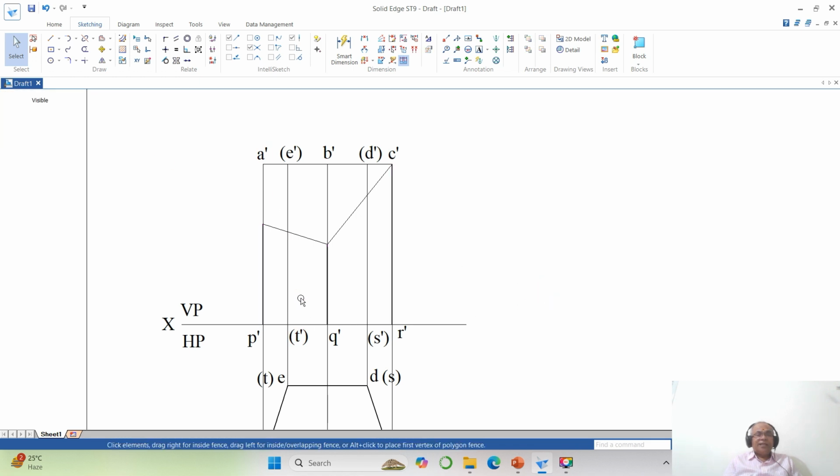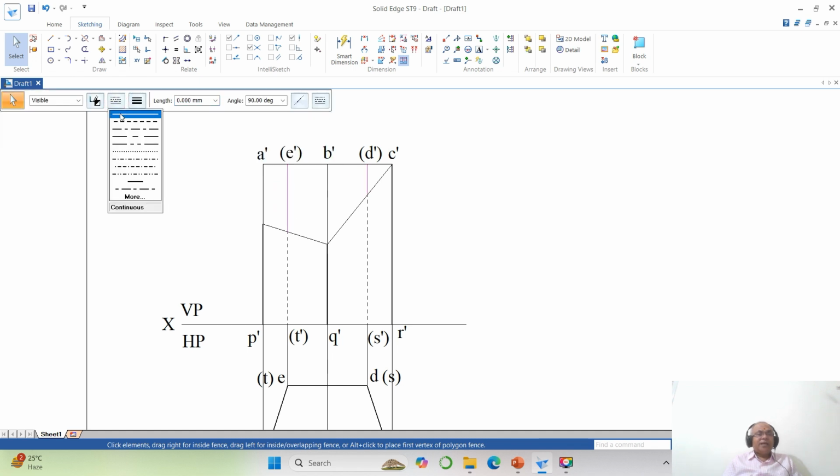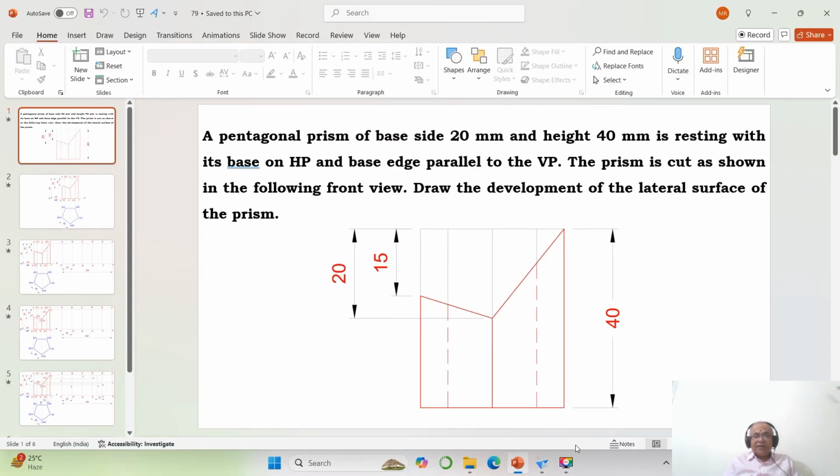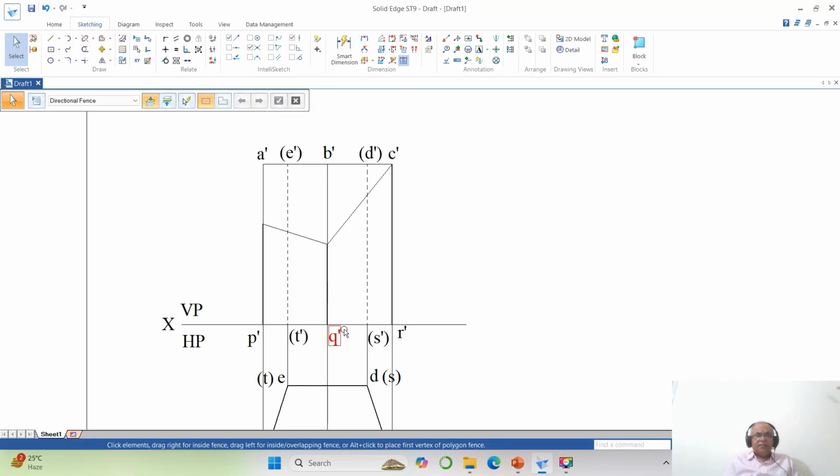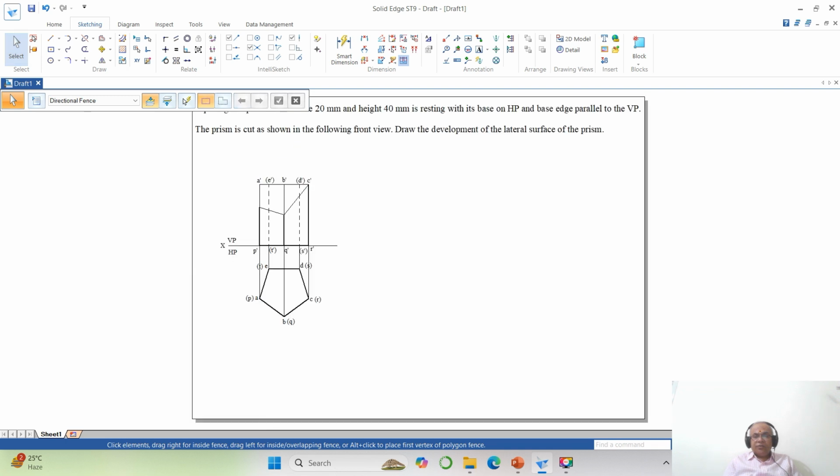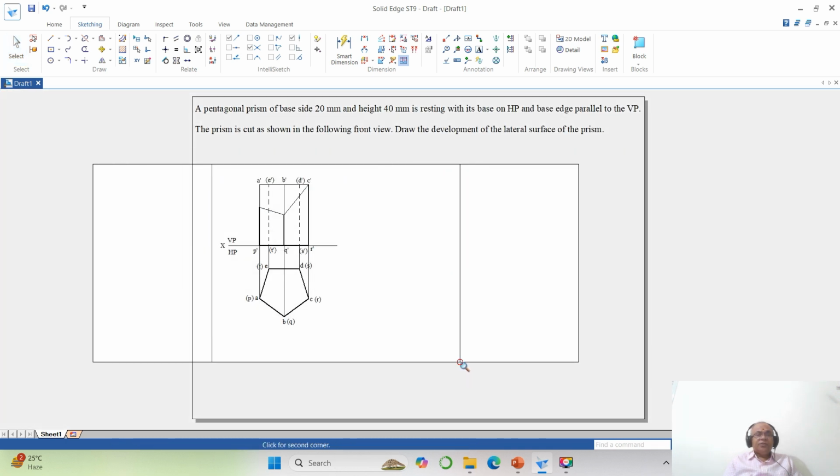Then you select this line and this line, which is a dotted line, and you make it 0.35. Similarly, you select between these two and make this a dotted line. Now when you see this and this, both should have the same figure with visible and invisible edges. So now we have the drawing which is completed. Now I go for fit, to show the dimensions.